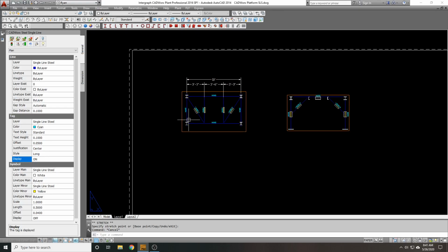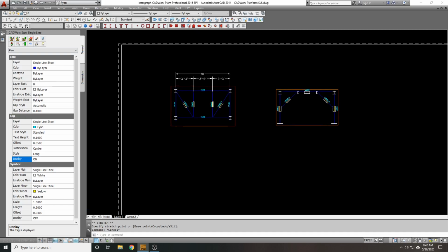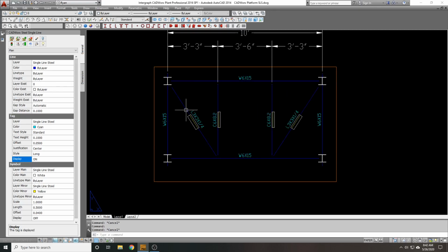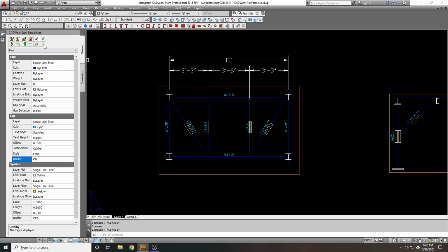That's pretty much it. That should give you a good starting point with how to work with single line. There are definitely going to be quirks. Things may not work the way you want them to, but you know now how to adjust settings, how to apply them to the viewport globally, or how to apply them to specific objects, how to load settings into the single line palette by just clicking a member. I didn't really finish going over the rest of these buttons. We went over the important ones, but we did the match setting. We know the adding a name setting, deleting a name setting.